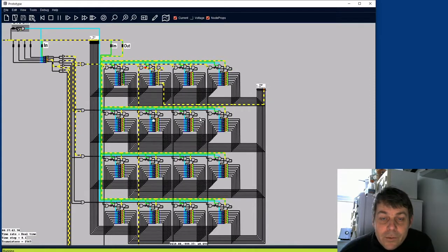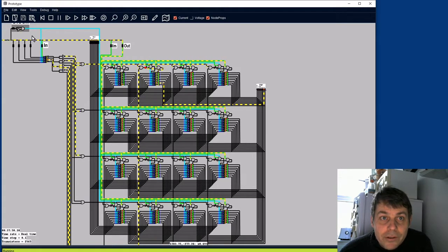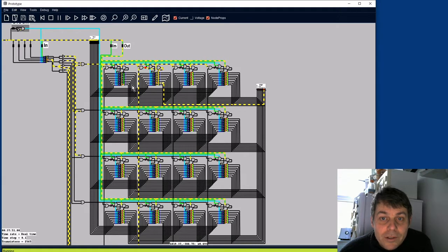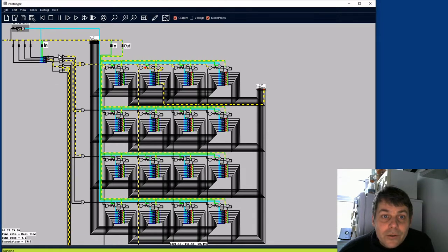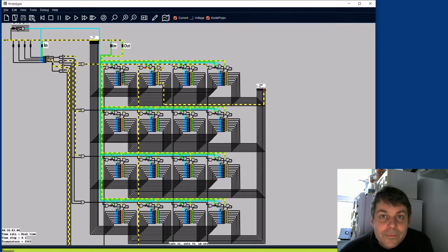So with this circuit we can select the address we want to use, and then we can input values from a bus according to the clock pulse. We can put those values in those cells, and then we can also address the memory and output the values back onto the bus. So now let's take this and add it to our model of a CPU.